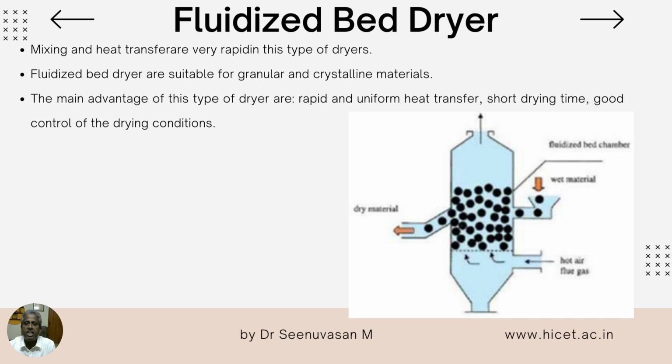Here, the residence time plays a vital role. The residence time is almost the same for all particles in the compartments, but the drying conditions can be changed from one compartment to another, and often the last compartment is fluidized with cold gas to cool the solid before discharge. This is all about the fluidized bed dryer.